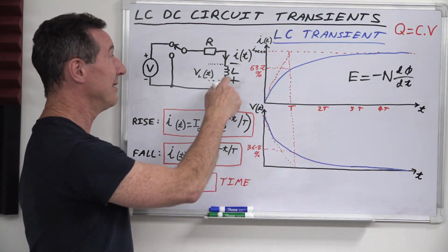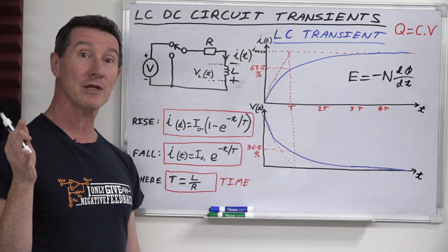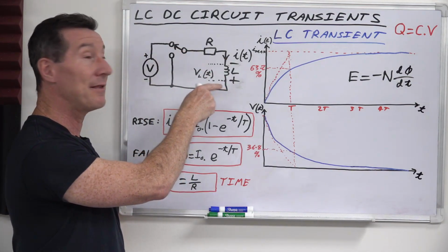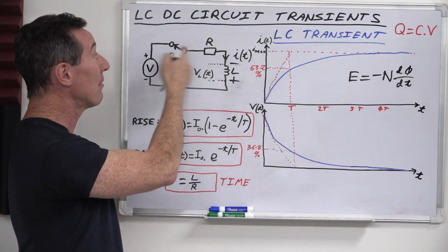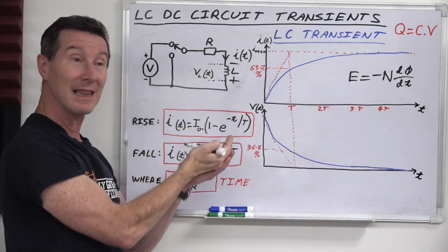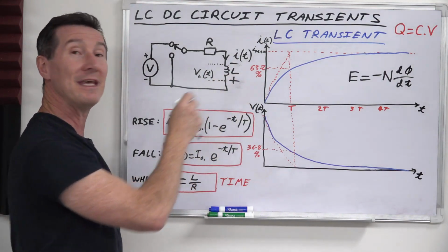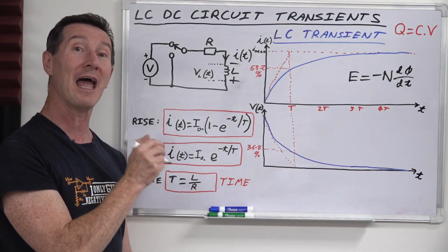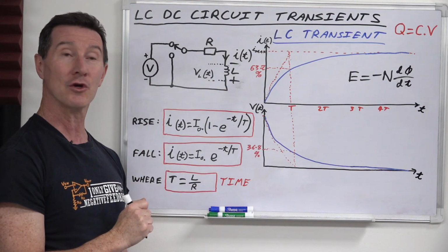But because of that, what are inductors used in? Relay coils, of course. So if your chip is driving a relay coil like this, and then you remove the current from the relay, the magnetic field of the relay is going to collapse. It'll generate a large negative voltage on the inductor, and that could blow your circuit up. So you've got to have reverse diode protection on your coil like this.